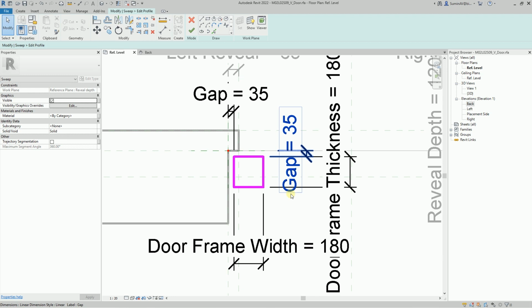Thus, all the lines of the profile sketch have a direct or indirect connection with the reference planes. That is, when the position of the reference planes changes, the sides of the rectangle connected to them through the gap parameter will move, and two other sides will follow after them. This is the effect you want to achieve when you sketch any geometric shape of the parametric family.